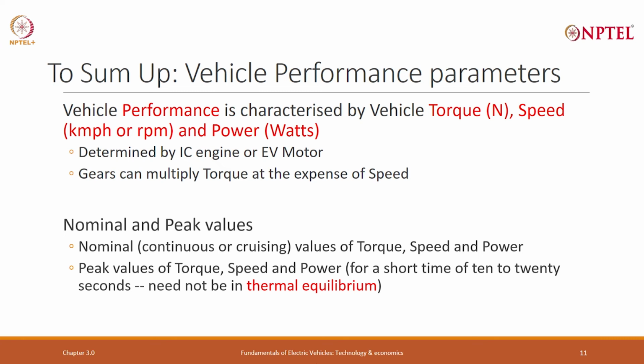It will start getting heated up. It is a thermal design of motor and controller which limits the power. 5 kilowatt, it can run for continuously. Whatever heat it generates, it can dissipate, the temperature will be constant. If instead of 5 kilowatt, I push it to 8 kilowatt, I can do this. I can do it for few seconds, maybe 10 seconds. After that, heating will start going up. If I continue it, it will blow the motor or impact the controller or impact the motor. For example, motor may have magnets which may get demagnetized.